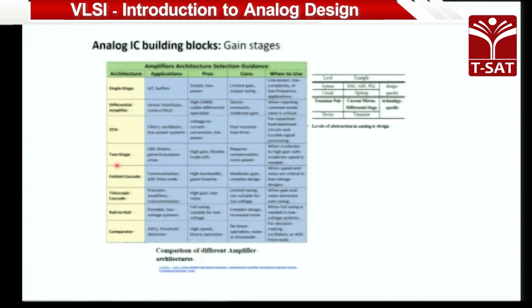As I said, analog signals are coming, and the continuous signal gets amplified, because these signals are very small. If I directly give these signals to the digital part, digital won't be able to take it, because digital does not know where the signal lies. Digital has only two things, on and off. So I have to define this small signal in such a way that the digital should be able to understand how to take this signal. So definitely I need amplification, I need to put it into an analog to digital converter, and then give it to the digital part. Okay.